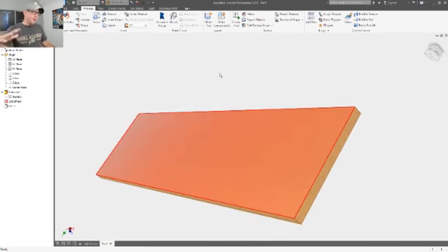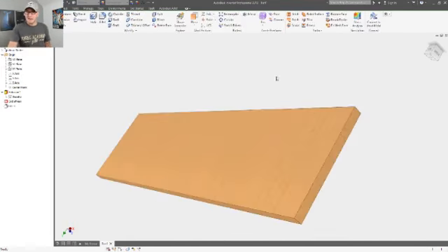And this always throws people off when you're doing materials with textures and patterns in them, because depending on the orientation you made the model, it really just throws that material on there in a generic way. The other thing you could do, I'm just going to back off of this a little bit. So I'll go back to my default, and I'll change this to a body.